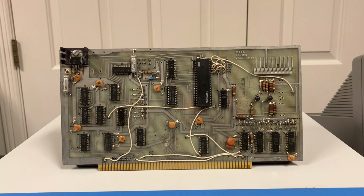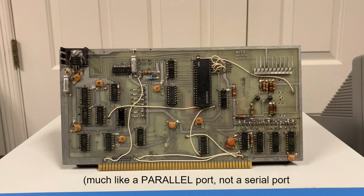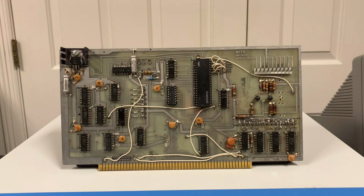And the reason for this is because the very first versions of the SIO board used a very odd protocol with the serial data. It actually required a handshake line between each character in each direction, both directions. Much like a serial port where you have a strobe when the data comes in and then another strobe for data going out. And so you probably have never seen a serial port that works that way. I haven't either. So it wasn't long until they quickly changed all these boards for the most part to use the more common serial interface.